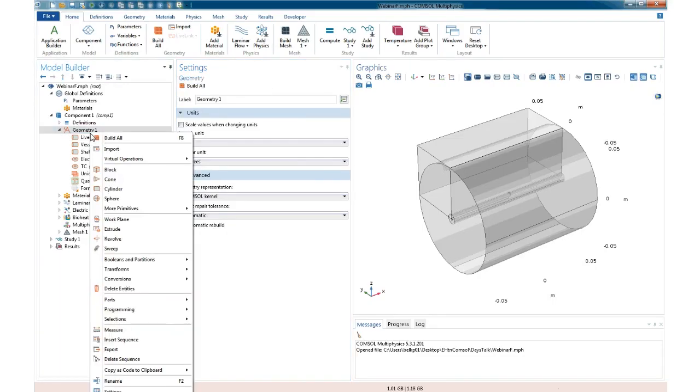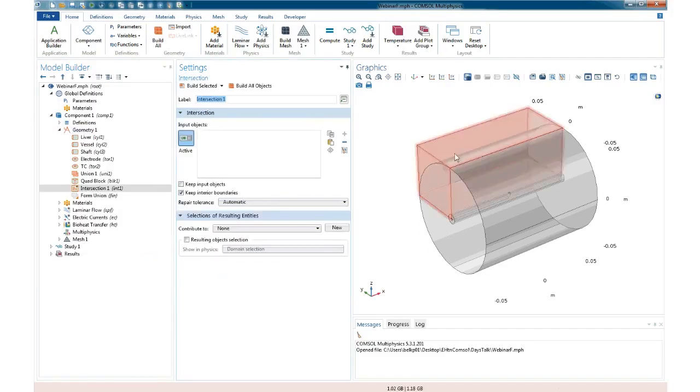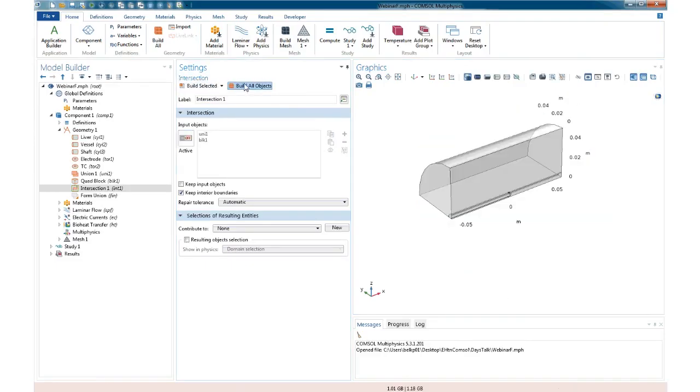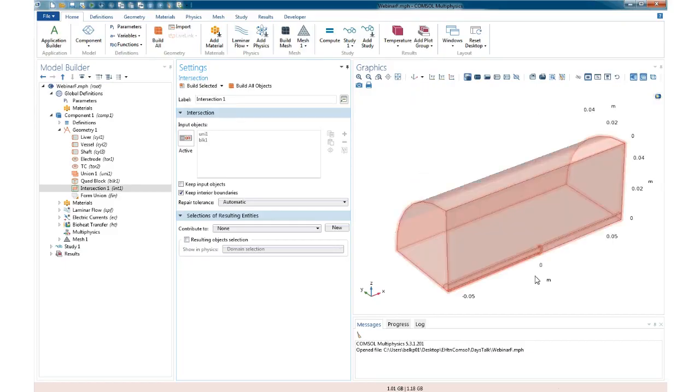Now you don't have to do this, but it'll make the simulation a little bit easier if you decide to. So let's build everything, and there it is. So now, by chopping out the 3/4 that really does the same thing as this 1/4 does, I've made life better for myself in a couple of ways. First of all, I've got a smaller system to simulate, so everything's going to go faster. But second, by chopping into this area here where all the action is really happening, I now don't have to look inside something to see what's going on. The most interesting things will be happening on this surface. And when we start graphing it, we'll see how useful that can be.